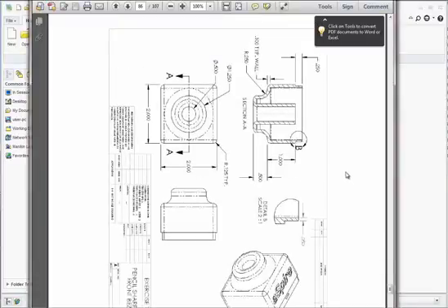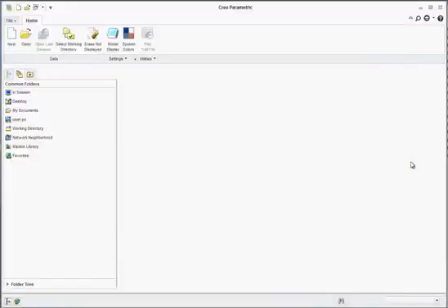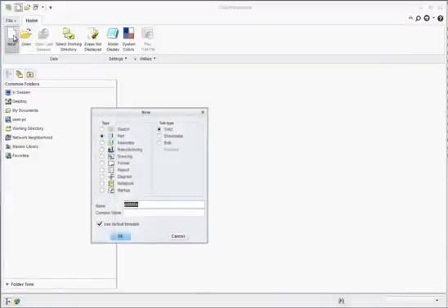And so from here, we're going to go ahead and draw this. The box is only a 2x2 square box. It's 1 inch thick. And so let's go ahead and build that out then. Begin with a new assembly and call it E9. Hit OK.